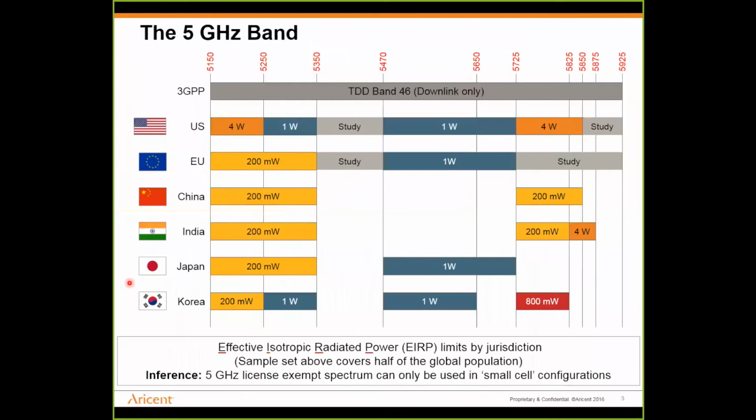But the most interesting bit of it is the 5 gigahertz band at this moment. That's because 2.4 is completely congested. We know all about it. 60 gigahertz is just coming up, and anyway, because of the physics of the thing, 60 gigahertz doesn't work beyond line of sight very well. The range is small. So the 5 gigahertz is the most interesting band.